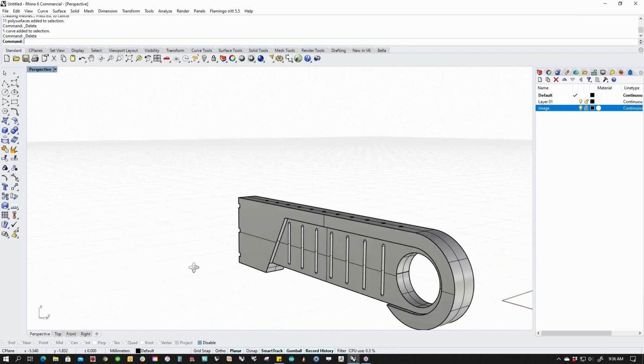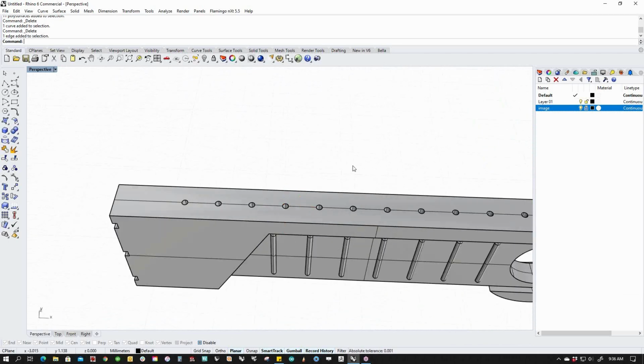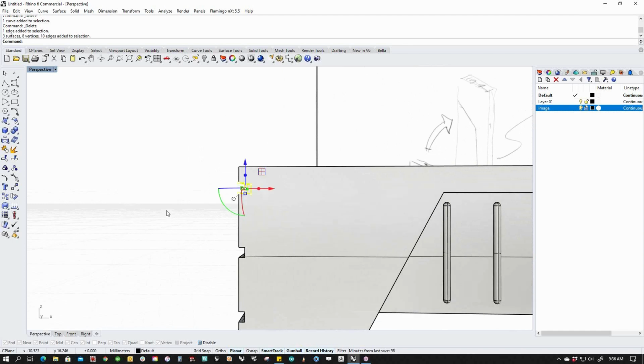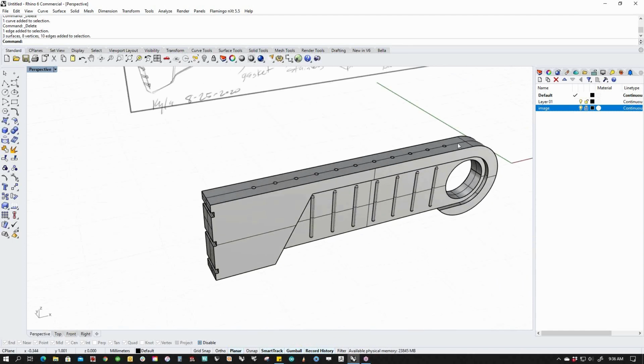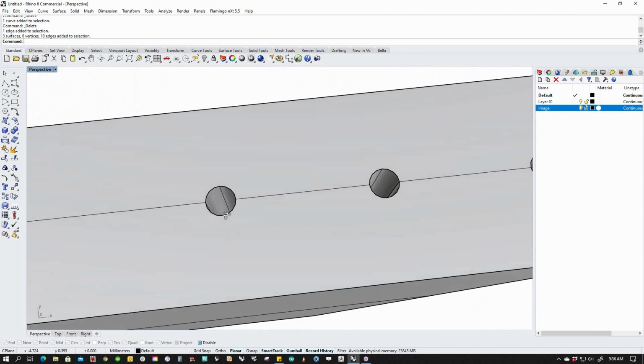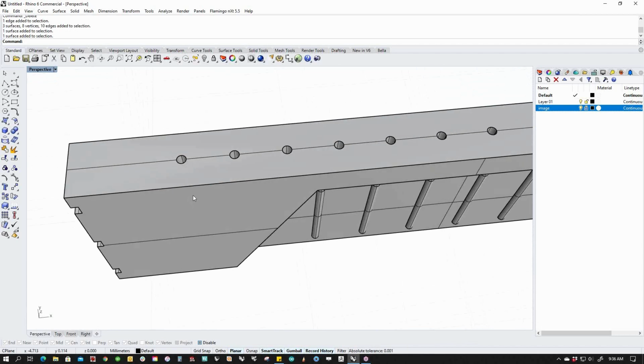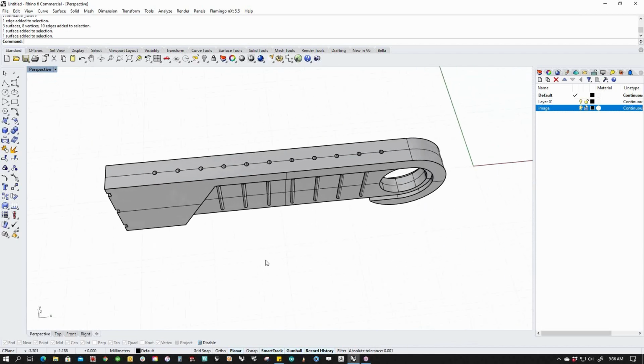What command do you use for cutting the holes? These holes up here, that was just a simple Boolean. These holes back here, that was wire cut. That was just a Boolean subtract that I did those. And if you look at them, they're actually capped with an inside because I just took that and jammed it in there and Booleaned it out.